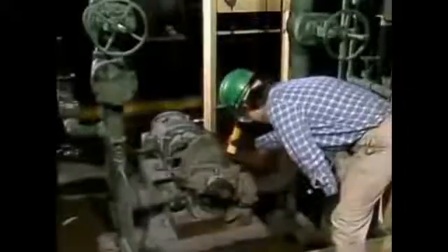Pumps that use packing often need a small amount of leak-off to cool and lubricate the packing. A trickle of liquid is normal. Unlike packing, mechanical seals should not have a noticeable leak-off. If liquid is leaking from a mechanical seal, the seal has failed and action should be taken to have the pump repaired. After checking packing or seals, the operator looks over the rest of the pump.